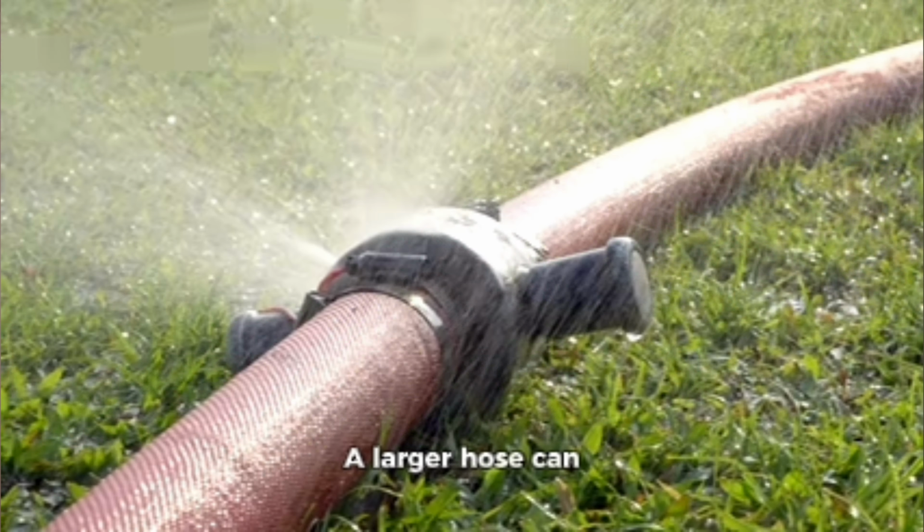That means if a faulty appliance leaks electricity, the ELCB will shut off the power before it can reach you. Choosing the right isolator and ELCB is critical. You need to make sure they can handle the total electrical load of your distribution board and provide adequate protection. Again, consult with the electrical codes and, if in doubt, call in a qualified electrician. They'll make sure your electrical system is safe and up to code.